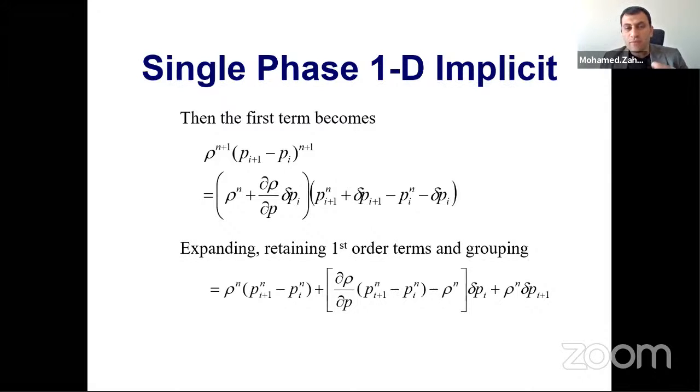And the pressure is different from one place to another. So if you ask me about the static volume, which is the initial oil in place, I can tell you the only impact of dynamic volume is how to calculate the fluid properties over distance, because over distance the pressure is not the same. Another factor from using dynamic is how to populate the saturation, because you need the saturation as well to calculate the hydrocarbon pore volume.